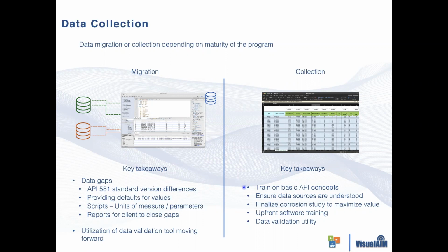We state this because in this particular project that we're referring to, the data collection portion was heavily performed by the customer. And at the early stages of this process, they were not super familiar with the API standard. So there were a lot of questions with respect to even, if I have a vessel, what components should I take of that vessel? What level of detail do I have to have? Even like the support is a particular component. Am I just sticking to a shell and head? Those sorts of questions. So if you're able to train on these basic concepts of the API very early on in the stages, not only of the data collection, but of the entire mechanical integrity process, you'll have a lot more success.